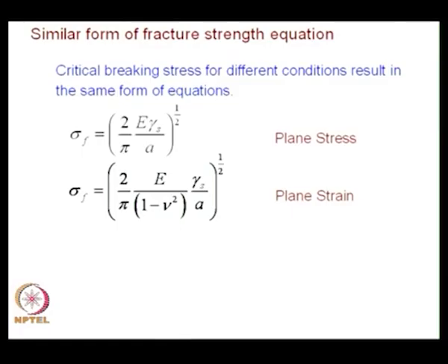In fact, you would come across this kind of modification in fracture mechanics. You will develop the expression for plane stress, then you can convert it to plane strain by changing Young's modulus by Young's modulus divided by 1 minus nu square. Vice versa, we can do that, and you get this for plane strain.